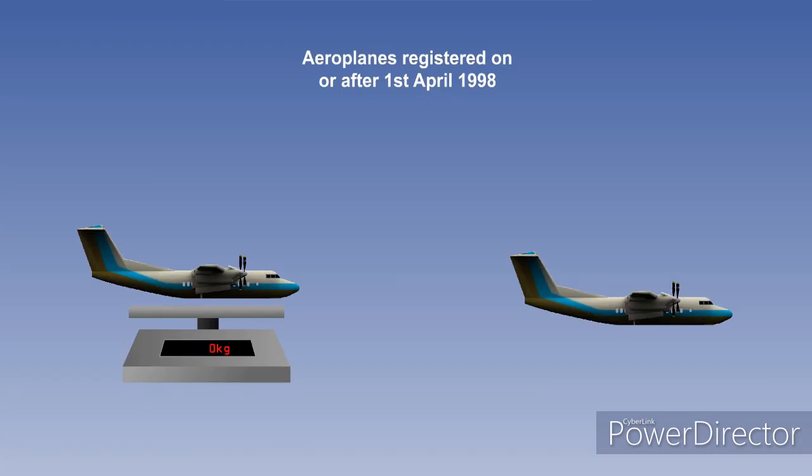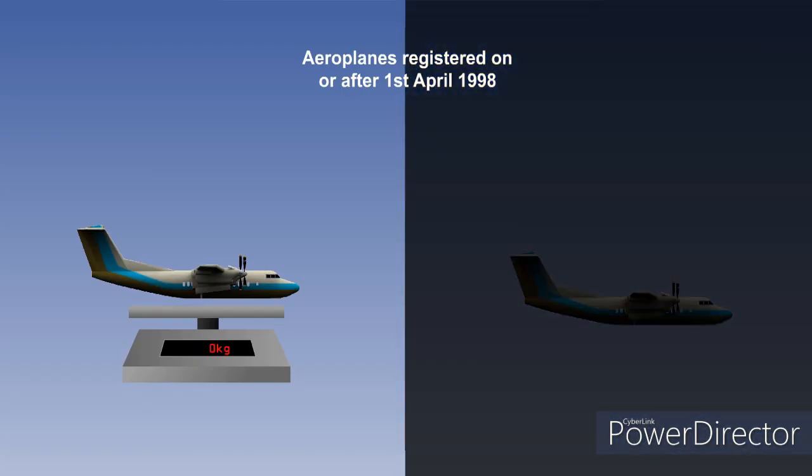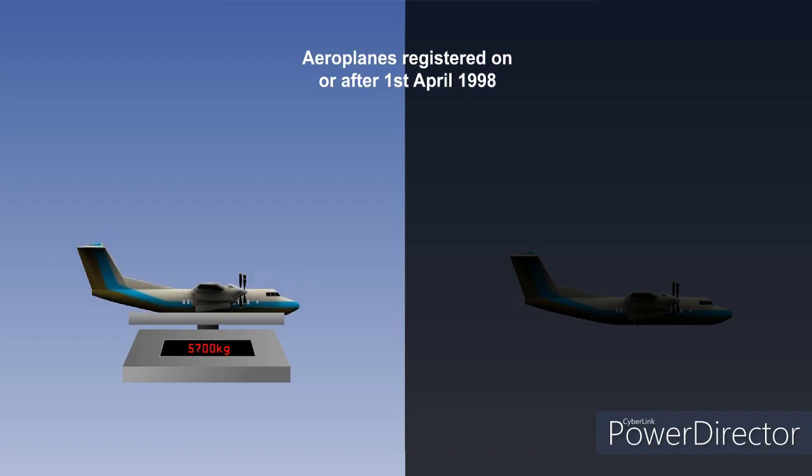EU OPS requires aeroplanes that are registered on or after 1st of April 1998 and having a maximum takeoff weight of 5,700 kilograms or less to be fitted with a digital flight data recorder that will record a minimum of the last 10 hours of operation.